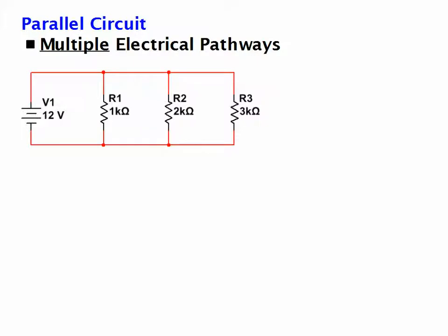Now basically, Kirchhoff's current law states that the amount of current coming into a branch, if we think of this, here's the negative end of our battery, as a faucet, turn on the faucet and electrons come out and they flow this way. The amount of current entering a branch equals the sum of the amount of current flowing through the other 2 branches. So this current here equals this current plus this current.